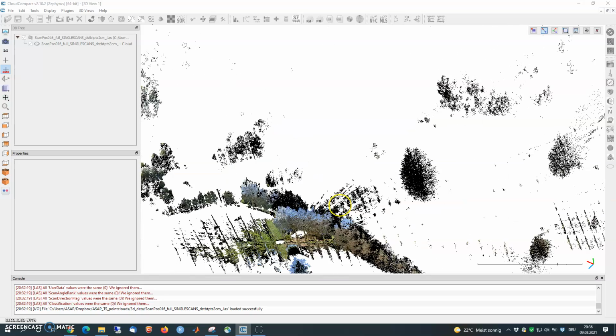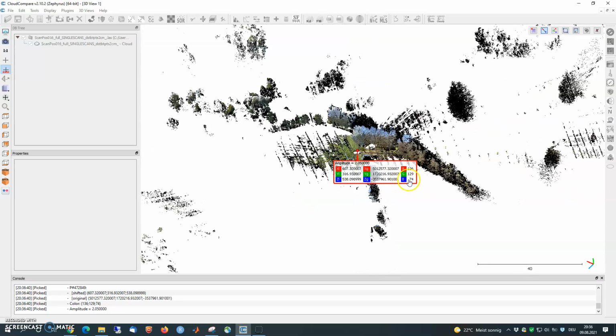And finally, you see here on the right, upper corner, we can select 2 points and display segment information, for example, length. So this is a way to measure distance. And then you click on it. So let's select a point in the middle of the scan. I choose here. You can say no for the moment. Oh, you already get some information. X, Y, Z, RGB. There we have.